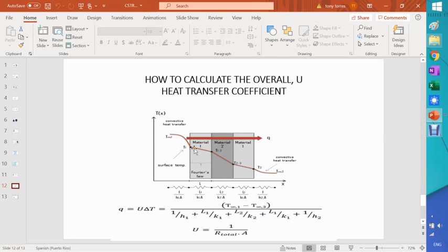Let's say that this is the glass lining, and that this one is between the glass and the metal, and the last one is the metal. So this is glass lining, and there's a resistance between the glass and the metal, which happens to be 0, because when they do this lining, it's totally very interesting how they do glass lining on this type of reactors. So this resistance has to be 0. Now you have the metal, which is about an inch, and eventually from there, you have another heat transfer coefficient that has to do with the jacket side.